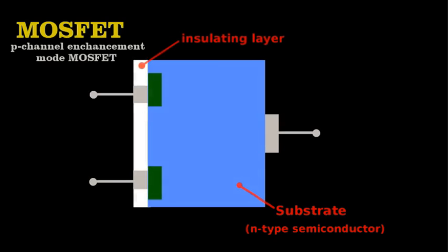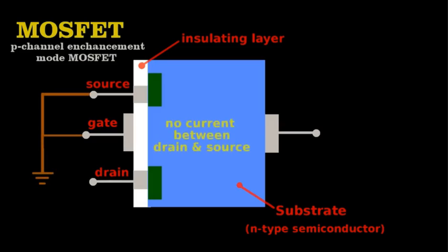Next, they coat the diodes with a thin layer of silicon dioxide. Unlike metals or semiconductors, this doesn't conduct electricity at all. On that, they place one more metal contact called the gate, which opens or closes the current channel between the source and the drain. When we create a voltage difference between the gate and the source, it generates a field through the insulating layer that draws the free positive charge carriers toward the gate, opening a channel that now allows current to flow.